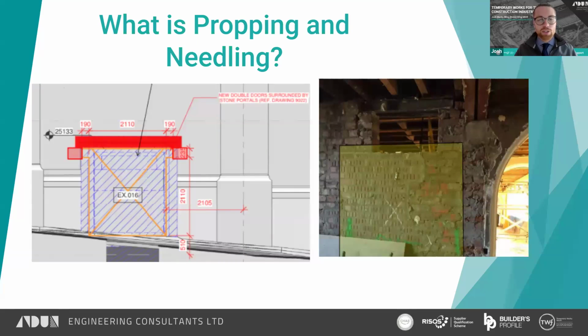It's the temporary works associated with creating openings in walls. I usually see these schemes in cut and carve demolition projects where the scope of work is to open up an enclosed area to create a nice open airy space, which is the trend for most contemporary office spaces or high-end commercial and sometimes residential buildings too. And so what we're looking at is how to make an opening in a load-bearing wall. A couple of examples of a typical scope are shown here.